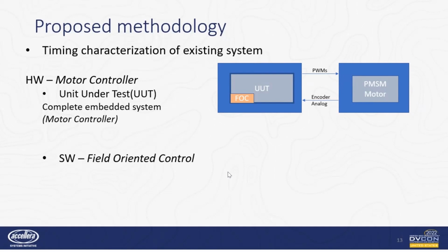The basic functionality of this unit under test is receiving basic user actions to control the motor, for example, start, stop, accelerate, and brake. Send PWM stimulus to the motor according to the requested action. Analog to digital conversion of the signals between motor and the unit under test and storage them in registers. Reporting of the motor status by the unit under test depending on the received information.